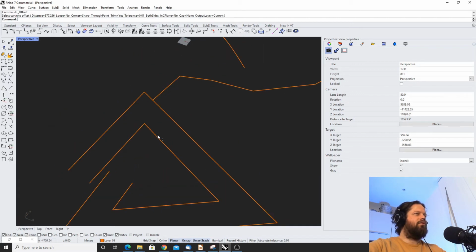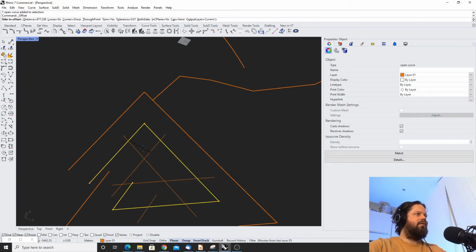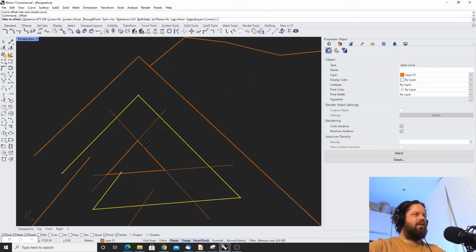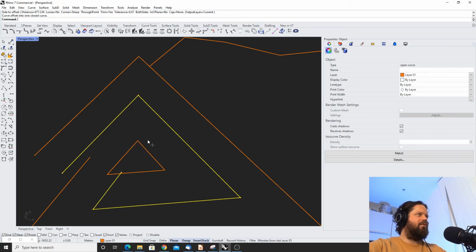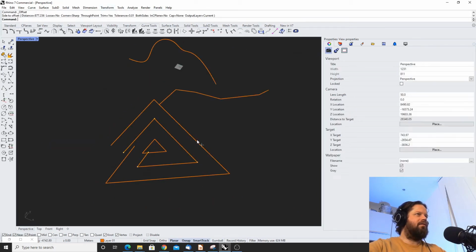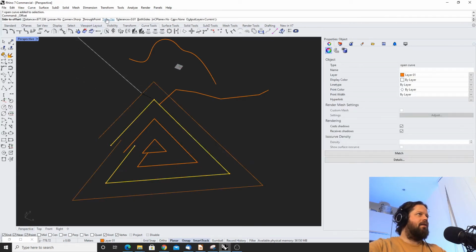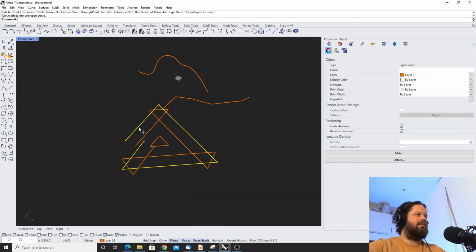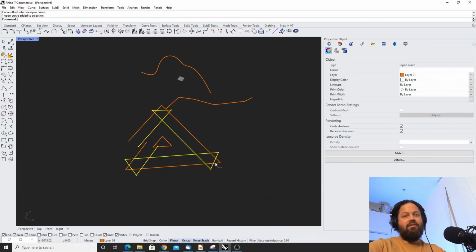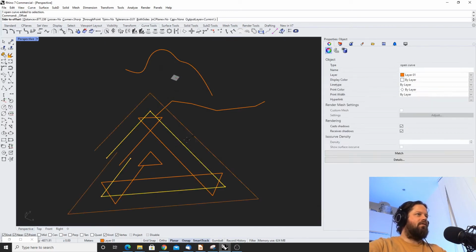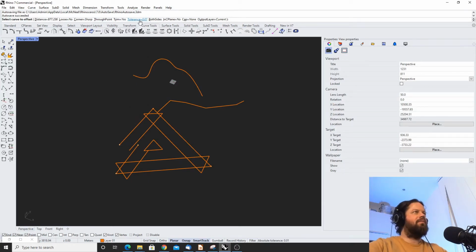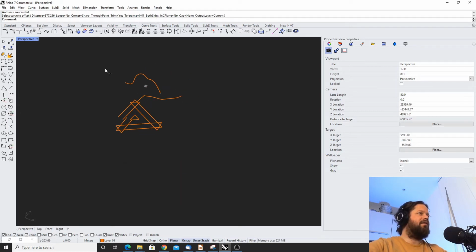Trim, yes and no. So what does that mean? If I offset to the inside, you see that it creates these extensions because this is the offset of the segments and it trims it off. If I don't have that on, then it does this. That's a bit weird, but it's interesting. Maybe sometimes it could be used. So again, trim, no trim. And tolerance, we'll not discuss today because that needs its own little video, I think. But we have other stuff here.